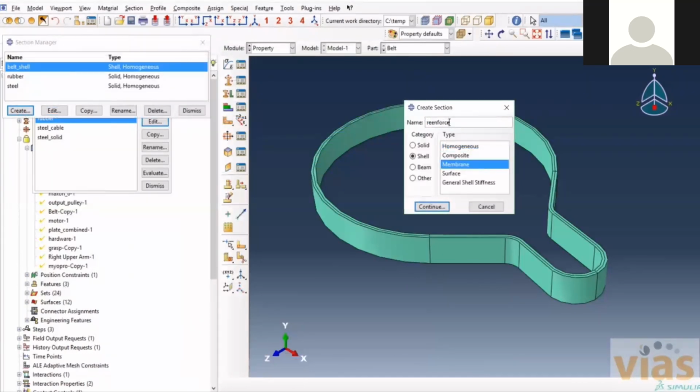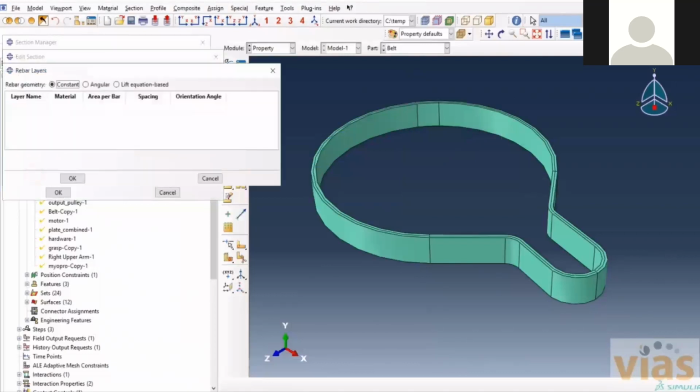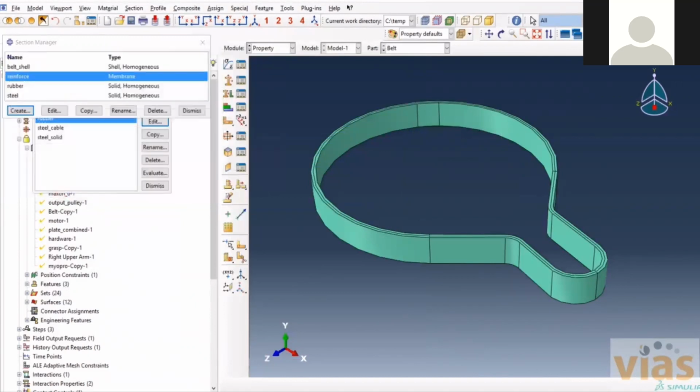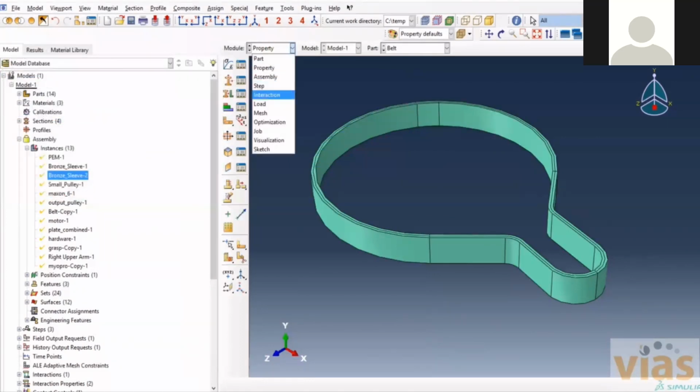You can define specifically what the thickness of that reinforcement is, what the spacing of it is, what the alignment is. As these are longitudinal, our angles for these would be 0. You can see that I'm putting the steel properties into that, and just providing some basic geometric definition. So we are able to capture quite a bit of the realistic material property for that.